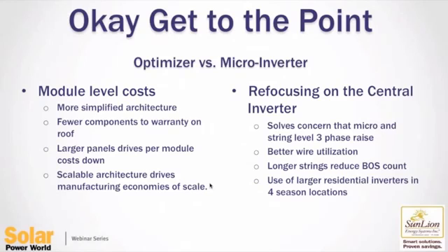We've been able to remove fuse combiners from most of our residential systems, and that has allowed us to remove the costly disconnect from the picture as well. So we've been able to remove complexity of the system by going to longer strings, by having better headroom. Most of the smart modules that are out now have 0% temperature correction. So VOC is VOC no matter where you put it in the world.